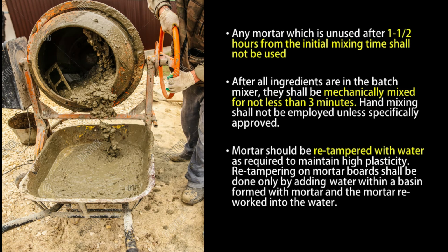Any mortar which is unused after 1.5 hours from the initial mixing time shall not be used. After all ingredients are in the batch mixer, they shall be mechanically mixed for not less than 3 minutes. Hand mixing shall not be employed unless specifically approved.